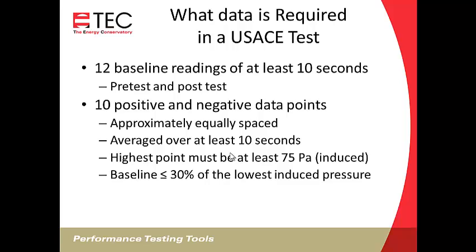And then you'll need to take 10 data points at positive, 10 at negative, and typically they're from about 20 pascals up to 75 pascals, 5 pascals apart, and you want them to be equally spaced. They need to be an average of at least 10 seconds. The default is 20 seconds in our software. The highest data point must be at least 75 pascals induced.